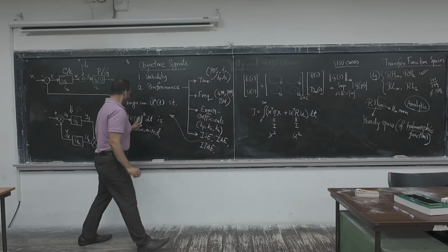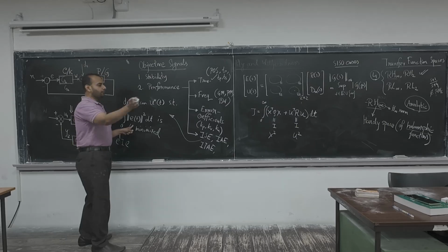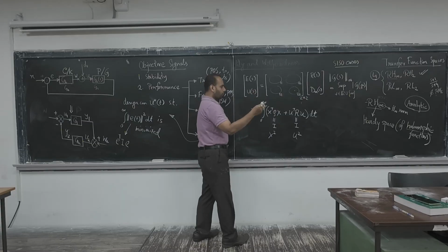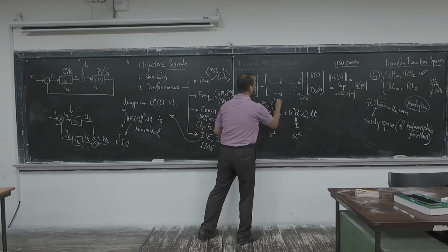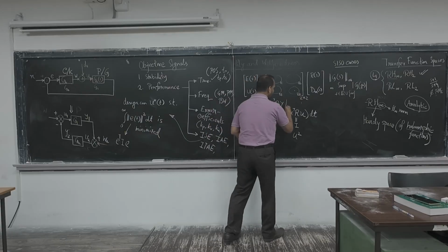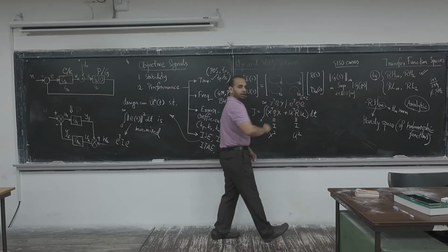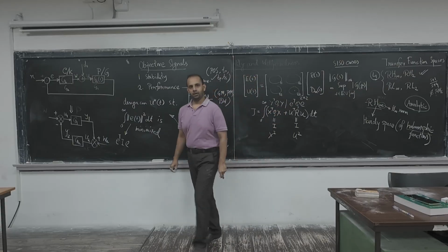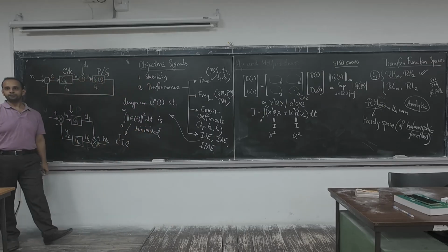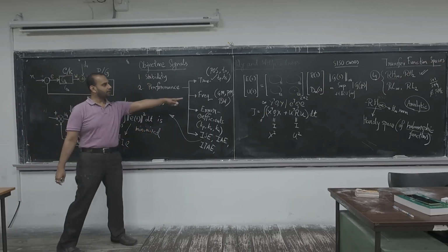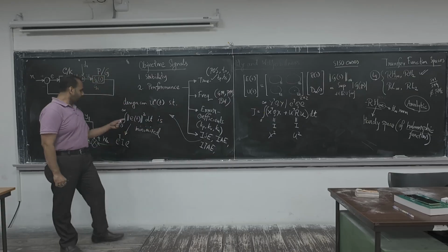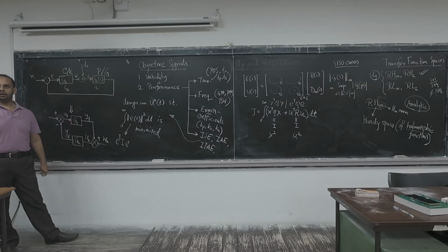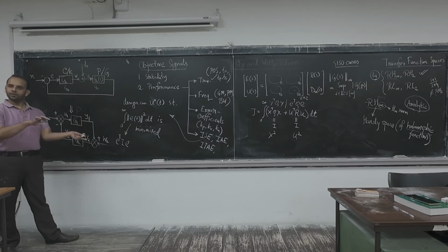Now, here we are dealing with E square. Or you have replaced this X, like suppose Y transpose QY, or there is another candidate, E transpose QE. Now a tracking problem means E transpose QE. Similar thing. But here Q is not fixed to I. There, Q is fixed to I. This is simply the integral square error minimization. So this is a version of that, but it has a different performance application.